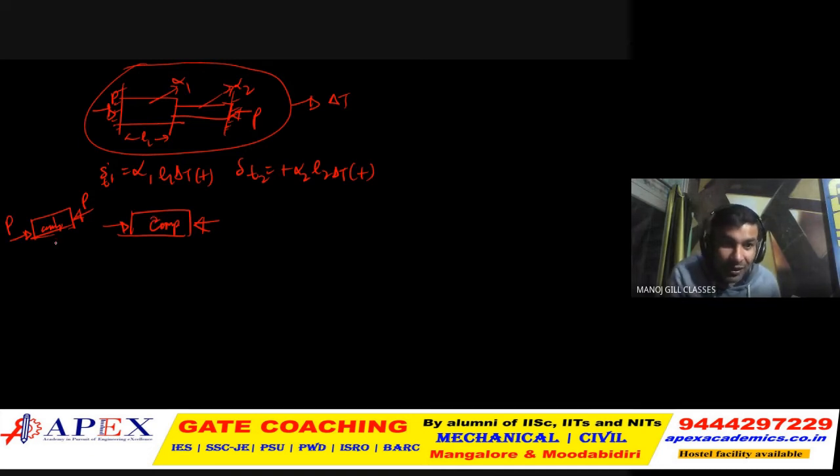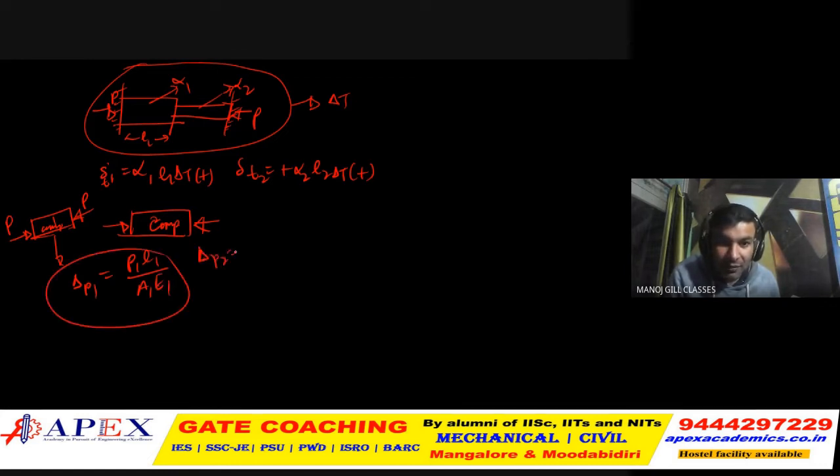So due to this, what will happen? The delta due to P in bar 1 will be equal to P1 L1 by A1 E1, where A1 is the cross-sectional area of the bar. Likewise for bar 2, delta P2 is P2 L2 by A2 E2. You will get this due to P.